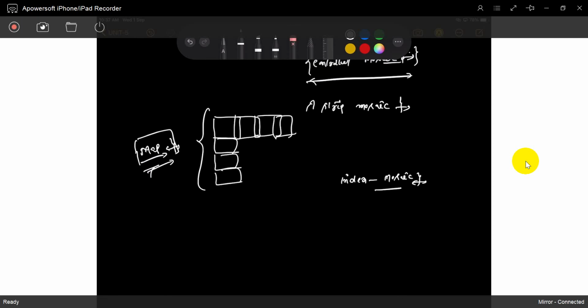There are no control points. You just use the photographs by matching the photos. If you feel an image fits, you fix it. There is no elevation difference, no horizontal control, nothing. No need to follow anything. Just by looking, if those images are matching, you take the images and match them. That is called an index mosaic.